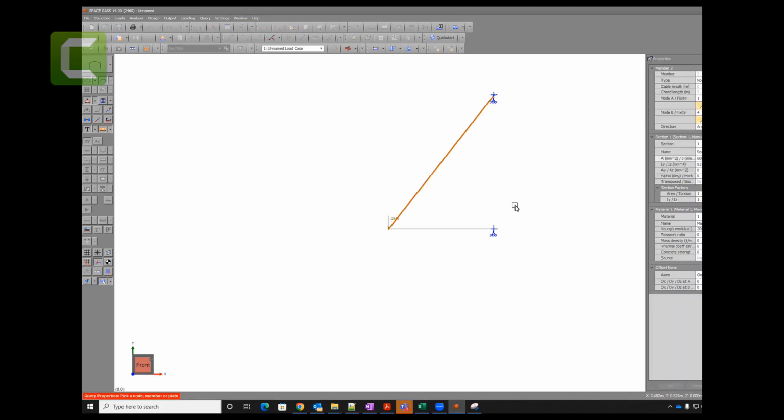If you want to see, you can just click on these and you will be able to see the members' size. Otherwise, we just keep it on the wireframe. And you don't need to do the second one. Otherwise, if you have different cross sections, you can do a second one. But once you've done the first one, it will have all the properties. We don't touch I and A and alpha and everything. We just need this Young modulus and this area. All right, so far so good. Anything else? I think we don't need anything.